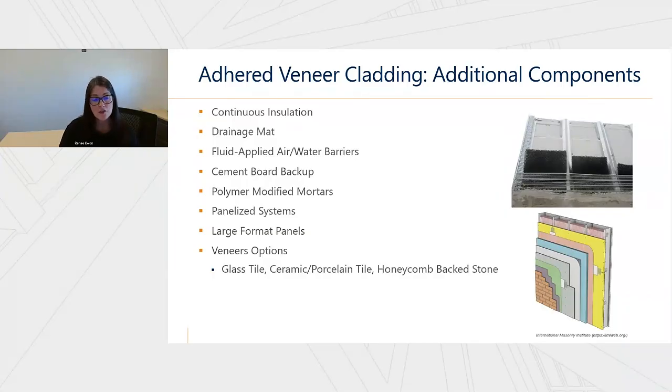But some of the issues we've seen with large format tiles, because of their size, they can be challenging to install properly, and making sure that all the ridges on the adhesive mortar are fully collapsed. And when I say ridges, we're talking about the adhesive mortar when it's troweled onto the backside of these large format tiles, and then it's placed onto the wall and worked into place.